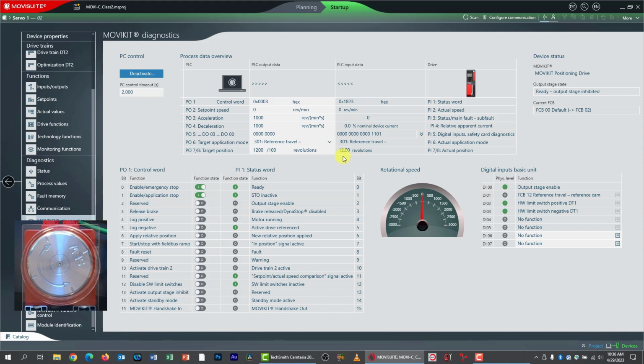I'm at the sensor, but I'm not at machine 0. If I were, it would be 0, but I'm at 12. And that's exactly what we're supposed to see. We're supposed to see the offset rather than 0. So there we go. That worked just fine. And of course, remember that sign on the offset indicates the relationship.